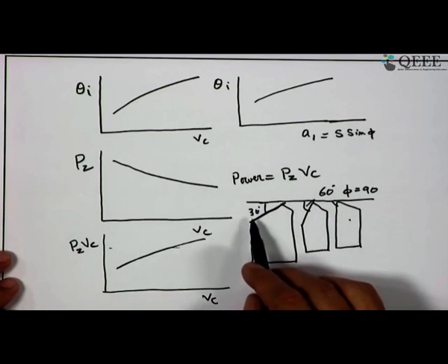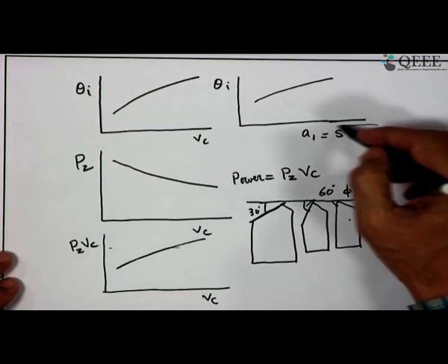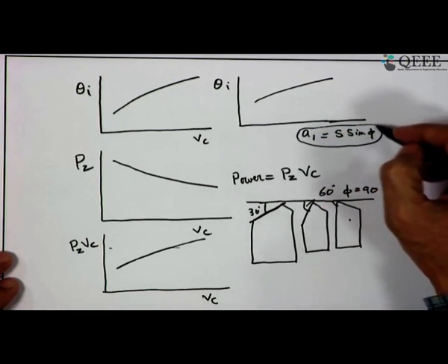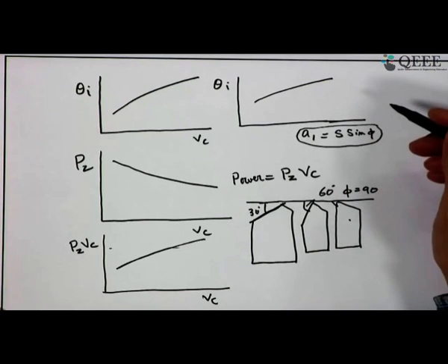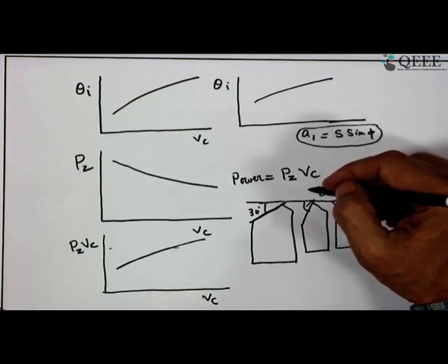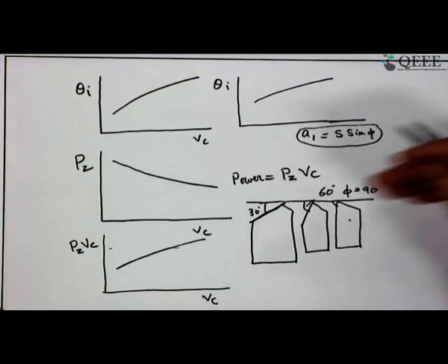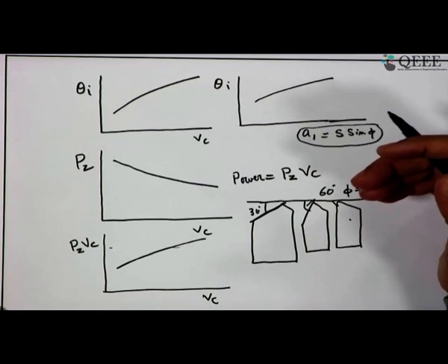So, what do 30, 60 and 90 degree mean? It is affecting the value of A1. That means, for the same value of feed, A1 is changing. When phi is large, A1 is large, and when phi is small, A1 is also small, but your rate of movement or material removal rate does not change.